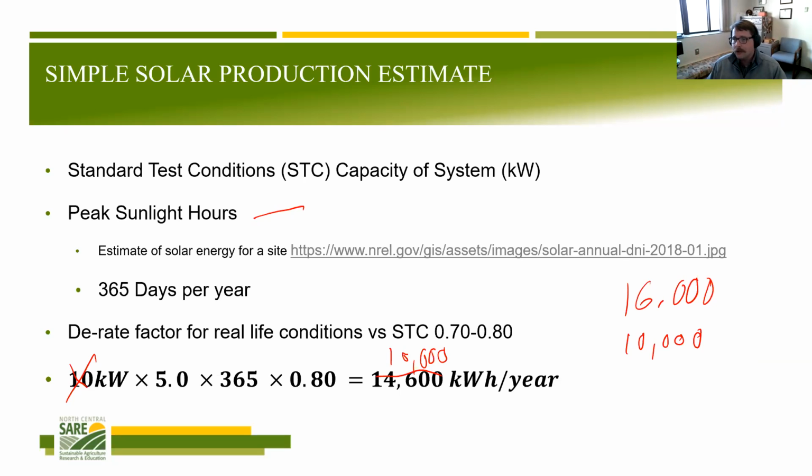So they actually do better in cold temperatures. They do worse in warm temperatures. But the fact is, it kind of balances out because it's not a large difference. And a lot of times when it's warmer, we have more hours of sunlight. So our summers are still our best production time, even though we have higher efficiency when it's colder. So the best production at any individual time period is usually in the spring and the fall, because I've got cooler days and the sunlight is beginning to be more direct.